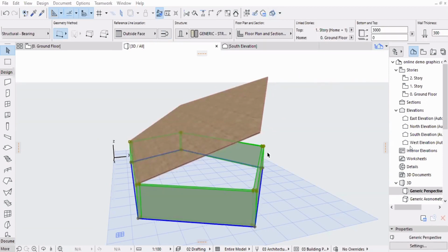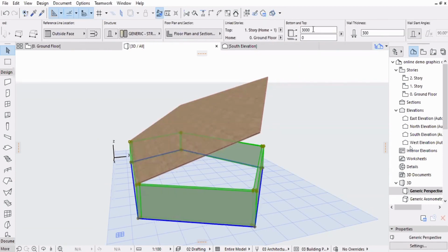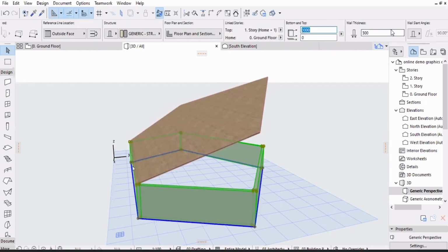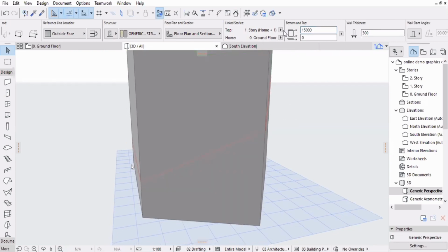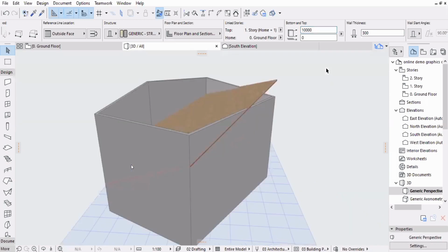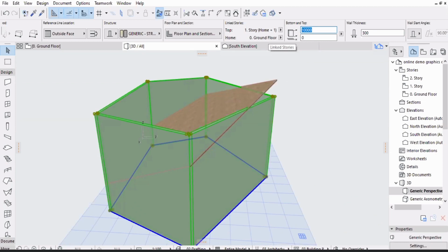Good. So I've selected the walls. I can simply come in on the Info Box and just change the height here. So I guess 15,000 should be okay. It's quite a bit. Change it to 12,000. I think this is a little less, so it needs to go beyond this. So maybe 12, 13,000 should work fine.